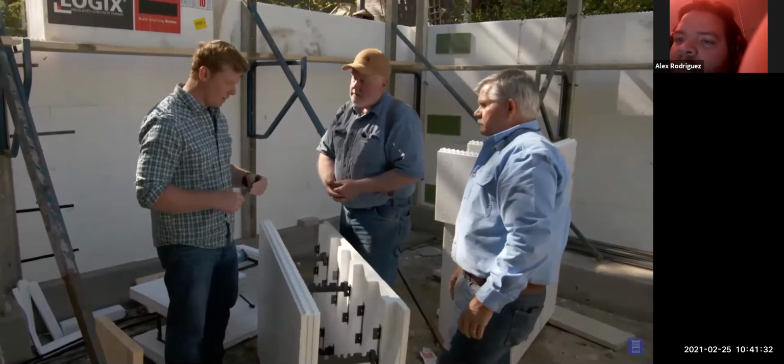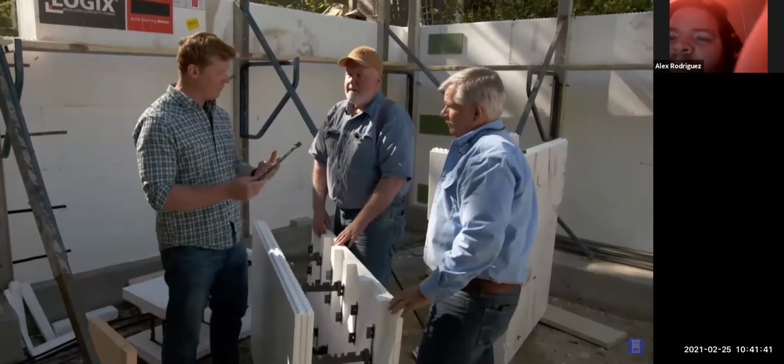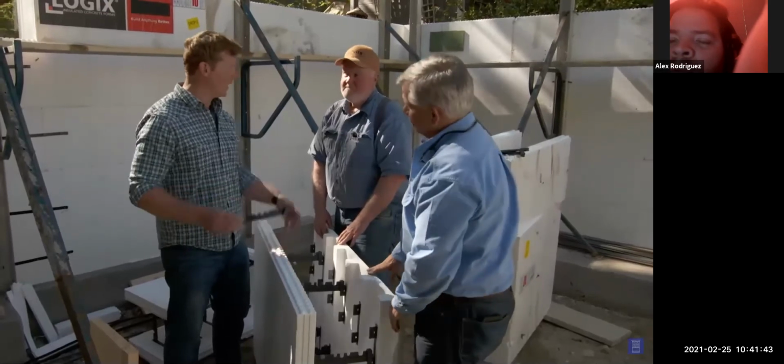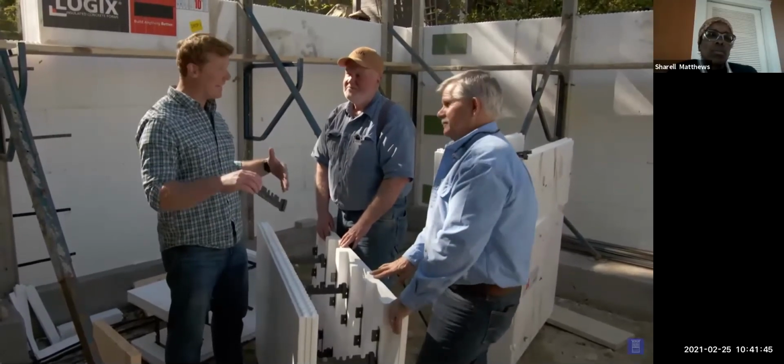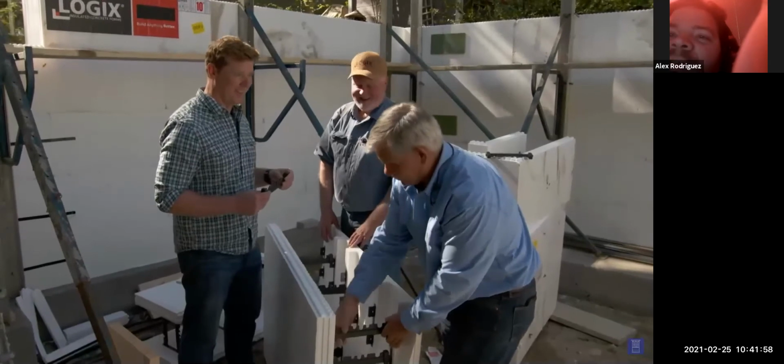Gotcha. And those are just snapping into place? They snap into place because we don't want the forms moving or shifting while we're casting them. Even though I've seen it before, when I hear that a piece of plastic and some foam is going to get filled up with all this concrete and stay together, it's a little implausible. How is that possible? Well, they're designed to carry 600 pounds at chest height when we're casting concrete into them. That's obviously more than the concrete weighs going in. They're pretty strong. All right, we'll find out in a few minutes.